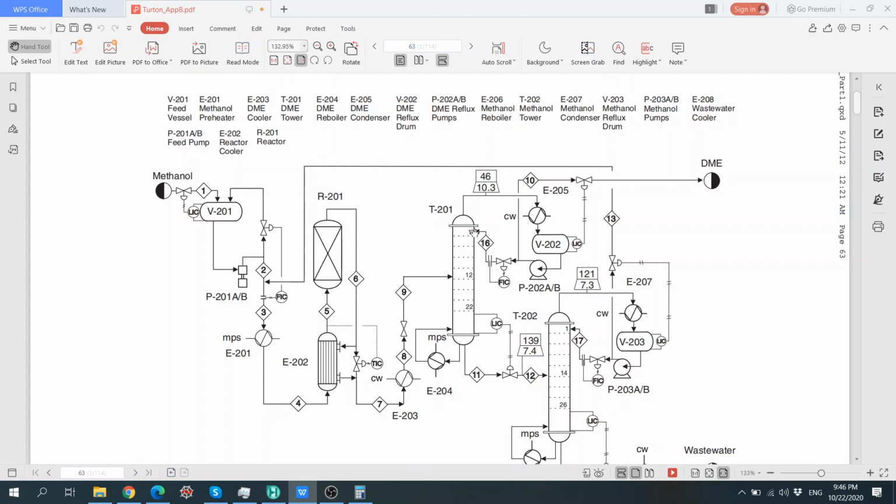So we are going to simulate 22 stages, and in this case, the liquid from the 22nd stage will go down to this collector, and then the liquid will pass through this reboiler and come back as a two-phase flow normally. So the vapor goes up and the liquid goes down.